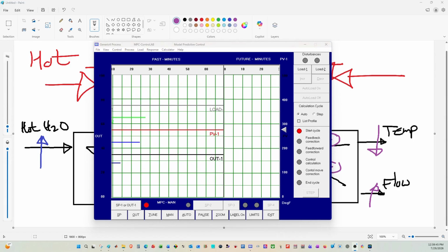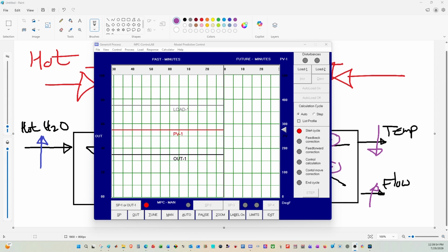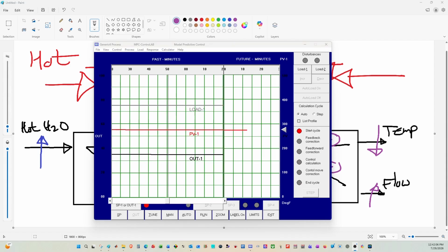For the sake of this part of the demonstration, I have substantially reduced all of the process variables that we can see. So I've taken a lot of it away, and it's just going to be a single input, single output controller. And I'll change it back to a multivariable controller at a later stage. My controller now is in automatic, and what I want you to have a look at is everything to the left of this very thick line that I'm marking out is the real-time information, and everything to the right of this thick line is going to be predicted information.